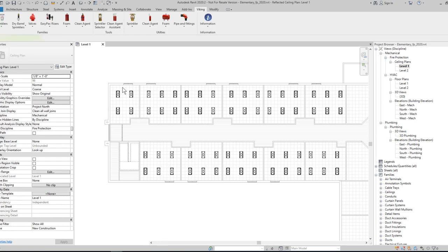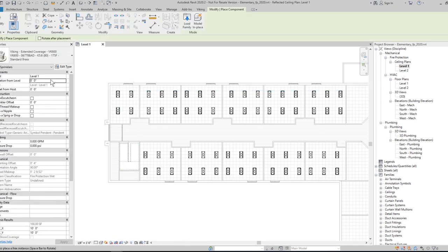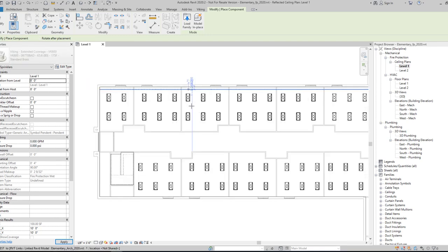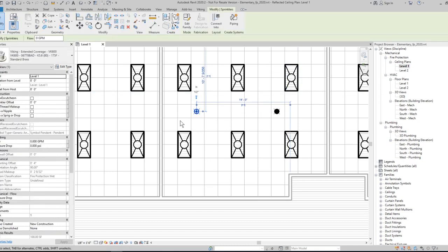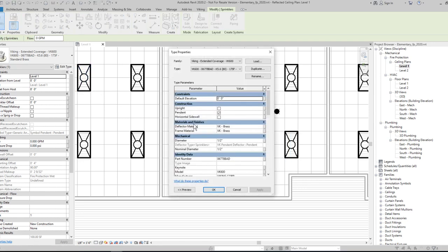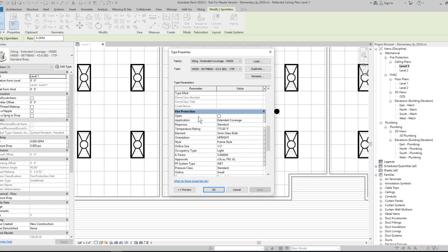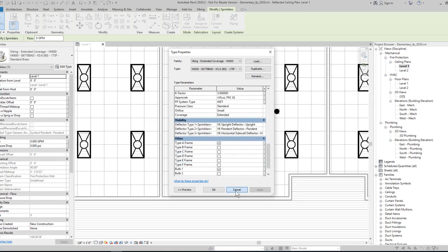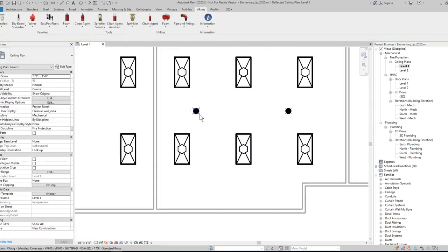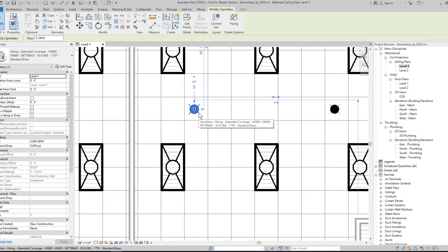This will then load this into my Revit model and queue it out for placement. As an example, I'll just place a couple here. If we were to look at this family and then the attributes, we would see that all the attributes are filled in as expected with the approvals, K-factor, occupancies they're intended to be used for, application type, etc. We'll also pull the annotation from NFPA, but this can be changed if you would like.